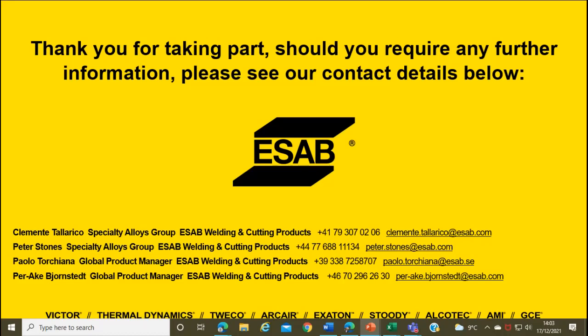Thank you, Peter. Usually we suggest adding at least 1/3 of new flux during the recycling, because of course some part of the flux on the weld pool will become slag, so it has to be scrapped. And then of course, by keeping recycling it, it will also deteriorate the grain size and the chemical properties of the flux. So at least 1/3 has to be added.